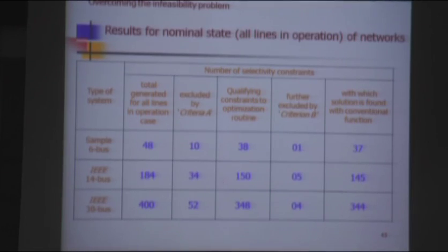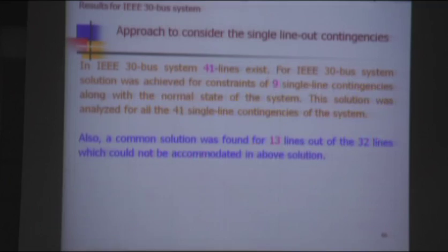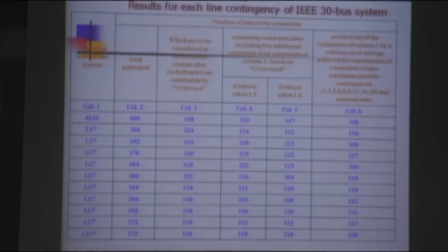It is easier said than done, because of the time needed for all the calculations: first the fault current calculation from all points, then deriving the mathematical problem, then finding the optimization solution, and then transferring the settings. This can be made possible in future, because nowadays microprocessor based protective relays are there, and with the advent of modern microprocessor relays, we can think of it in the near future.